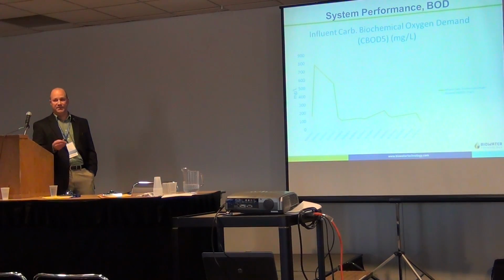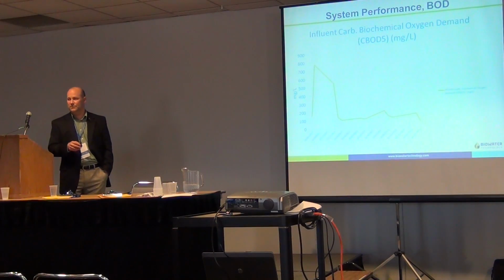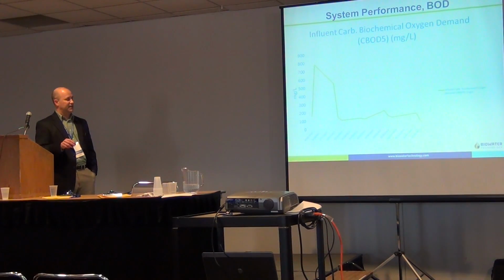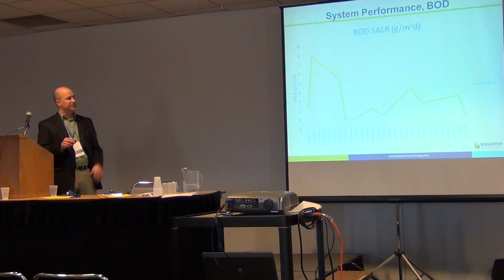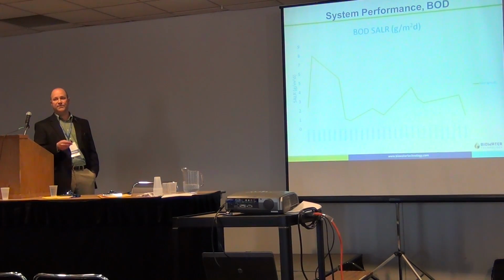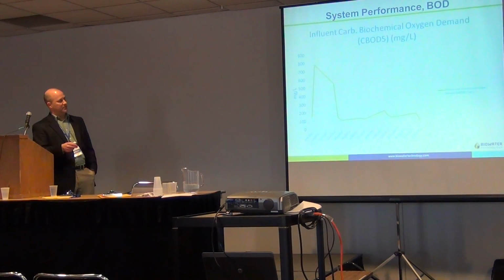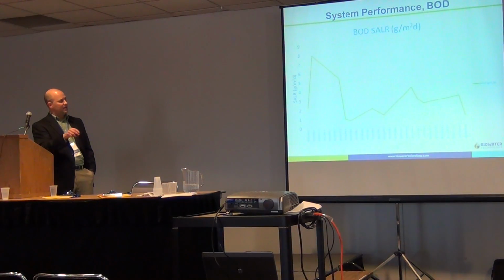So this process really had to be designed to handle some very changing scenarios. Again, when we talk about surface area loading rate, that's the square meters or square feet of the media in the tank and how many grams or pounds you can load to that. So you'll notice going back and forth between the soluble COD in milligrams per liter, taking the flow into consideration, and looking at the surface area loading rate. The graph changes a little bit.